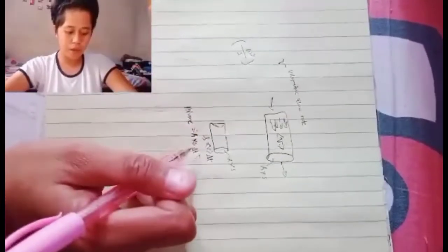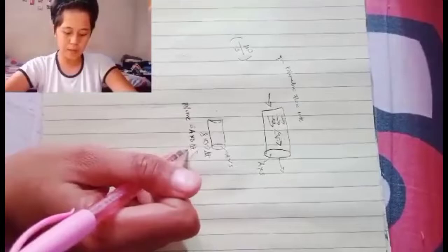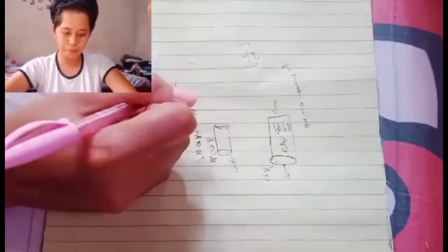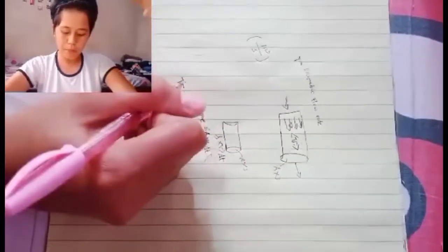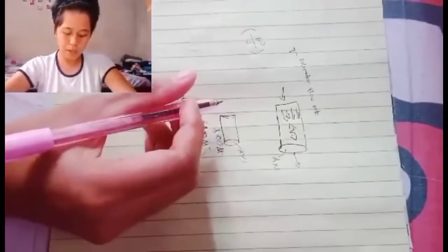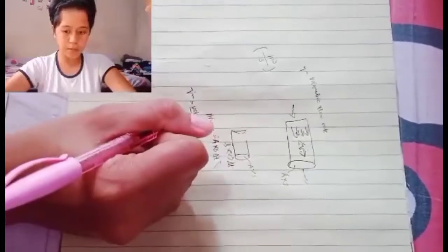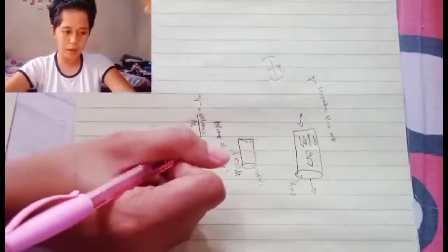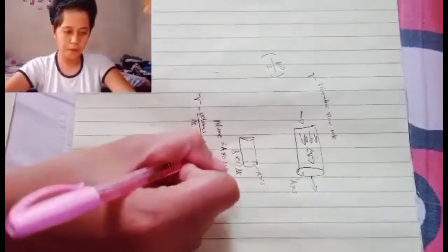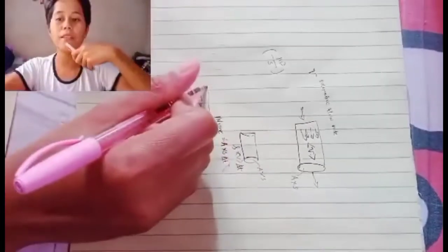And then to get the V dot, we're just going to move the delta t to the other side. So the volumetric flow rate, the volume per time, is going to be the volume divided by the time interval, and so that's just going to be the cross-sectional area times the average velocity. That's a very simple relationship, but sometimes it's one that we miss.